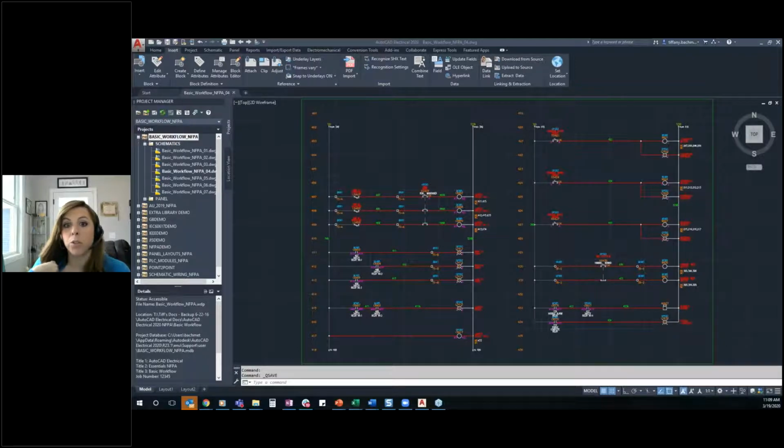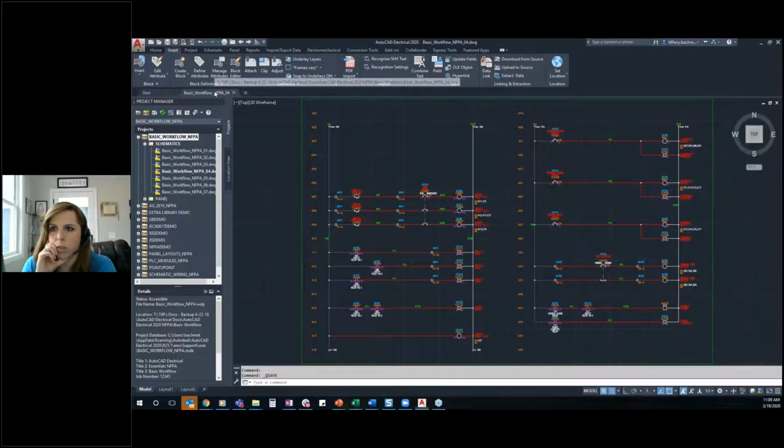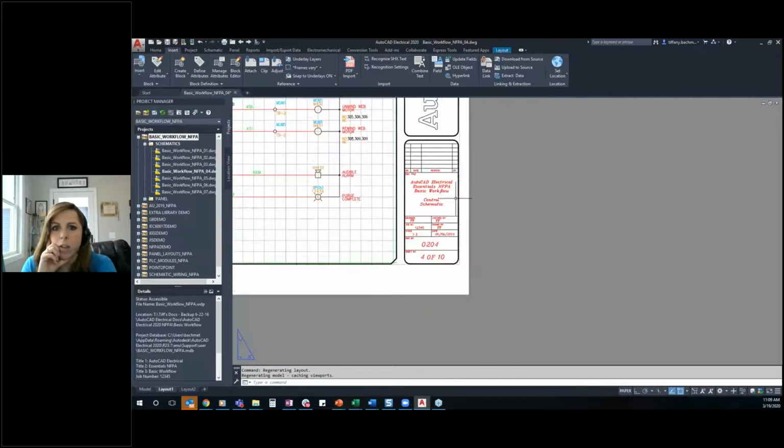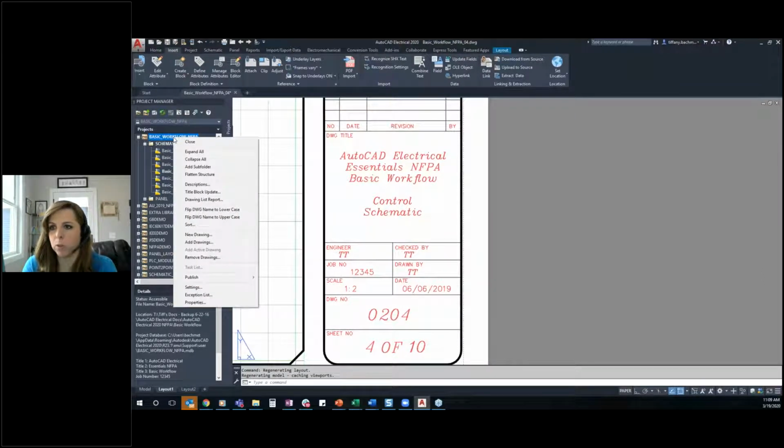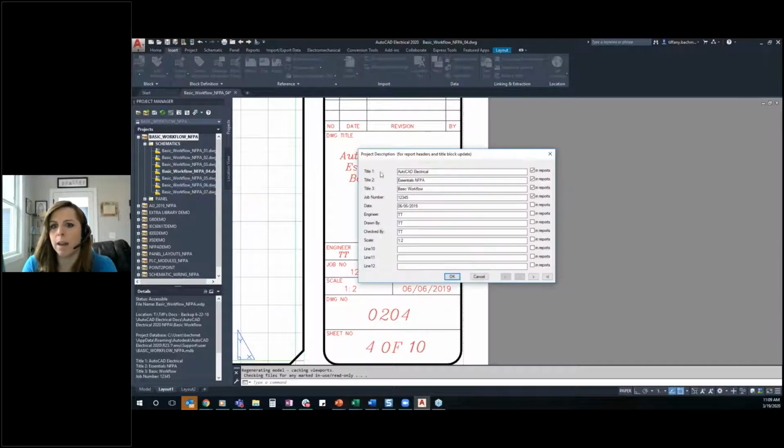So you can actually edit within Electrical when you create, and if I were to switch over to a title block here, any open attributes that you have, you can link to being project or drawing attributes, and you have unlimited opportunities to do this in this description area. Within the projects, you can see I can keep going hundreds and hundreds of lines.